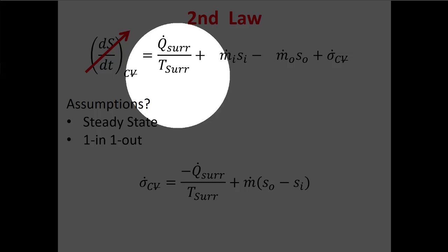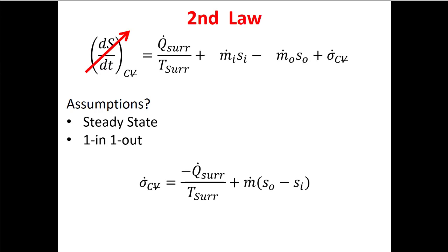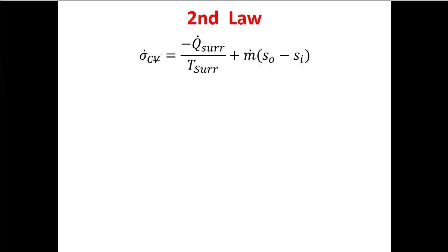So I've got to use the temperature from outside of my system. Technically, I think it's the temperature on the boundary, but usually we use the temperature outside of the system in this analysis. So it's not the 100 degrees inside the system. It's whatever we said, 40 degrees, but even that's not right because we've got to add 273 to it.